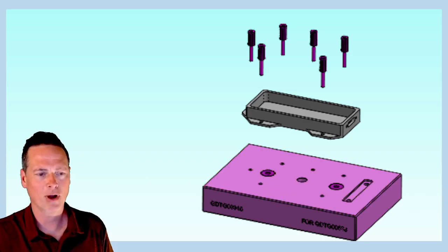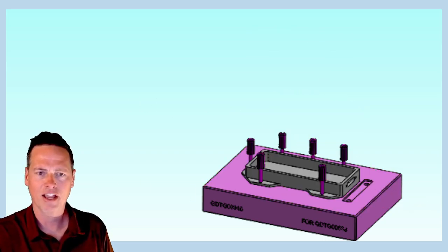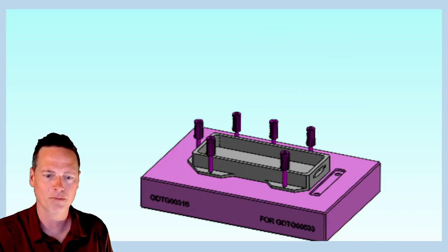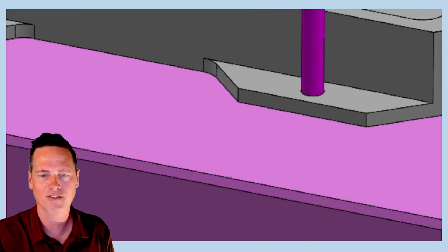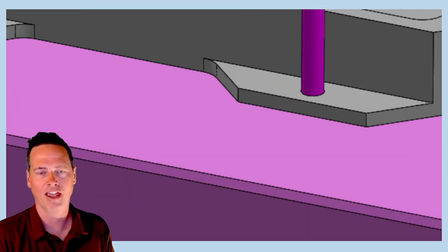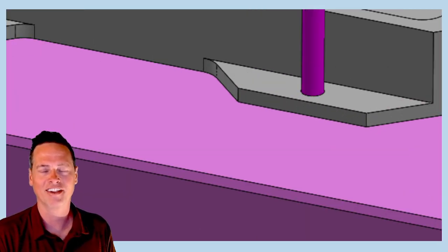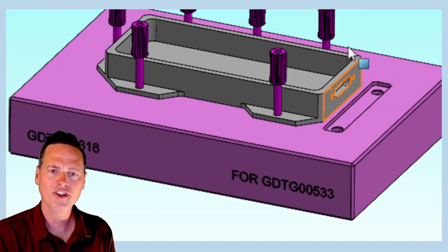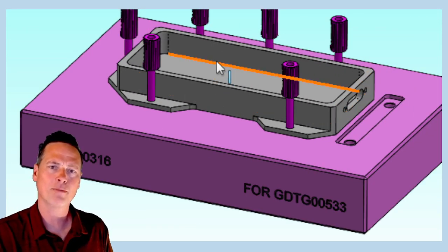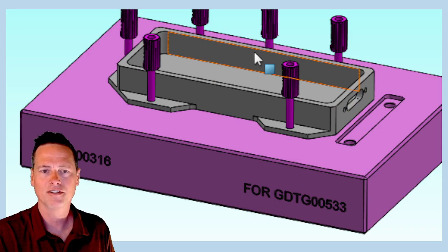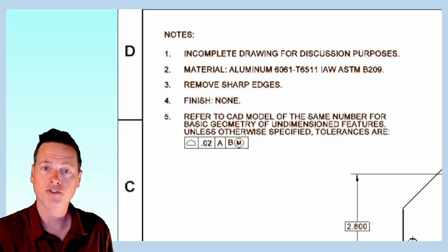And then I can set my part down on the fixture, and I can use special hole locator pins to verify the position of the screw holes in that datum A primary, B secondary datum reference frame. And this all makes a lot of sense because those holes are part of that same interface. And back to the drawing real quick.